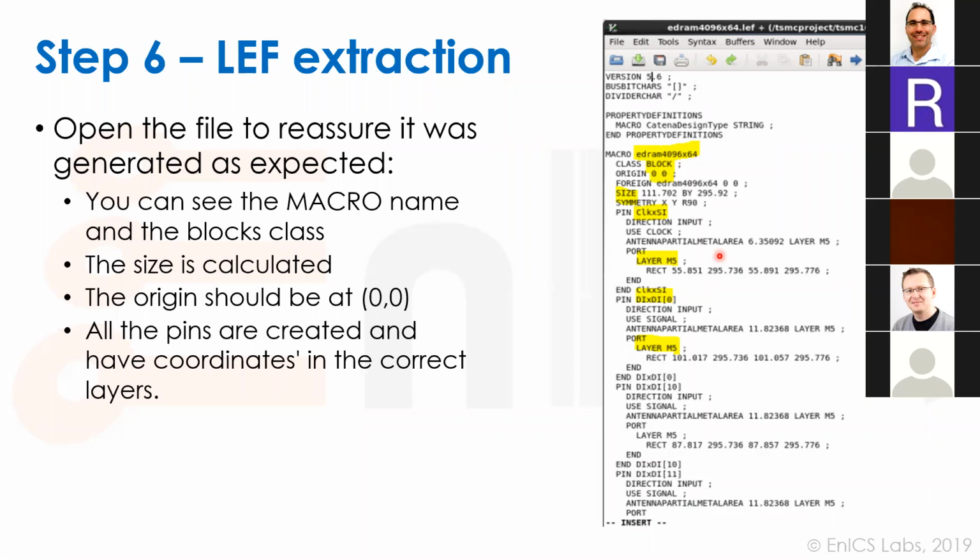And if enough charge is deposited, similar to static electricity, when you touch somebody and you get an electric shock, it will build up so much voltage that it will break the oxide of the transistors and burn out the chip. So this has to do with the amount of metal layer that is not grounded through something that can be grounded, versus the amount of oxide that will be burned out if too much charge is on it.